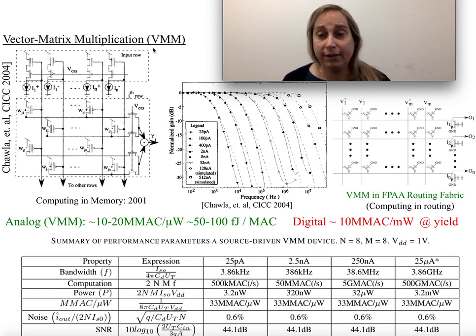If you look at the early elements and discussions in the neural network community, which is where a lot of this started, in the early 80s to mid 80s to late 80s to early 90s, the struggle was how to store these values and still use them in a multiplication. Eventually the conversation was that a single floating gate element really is the key element you want. You can talk about other crossbar elements, but it still is by far the shining opportunity here. It is a beautiful three or four terminal device, depending on how you look at it.